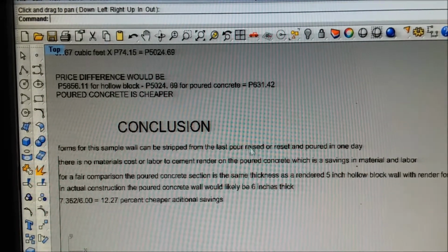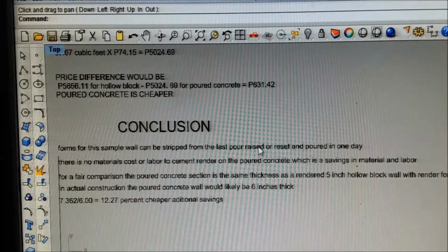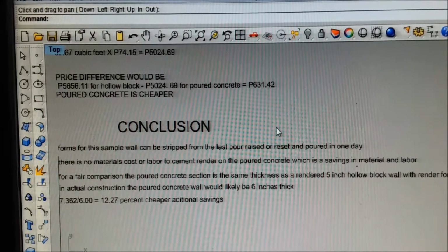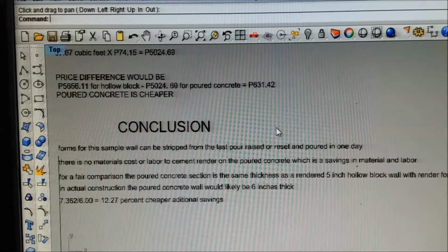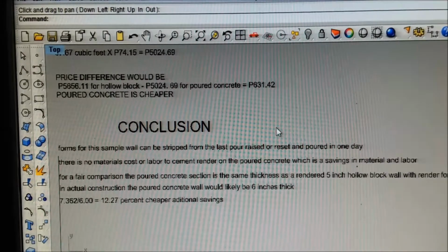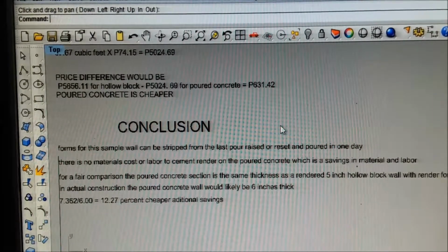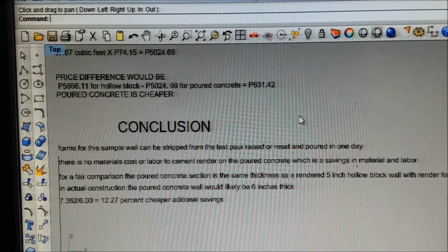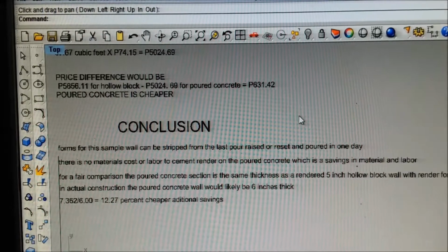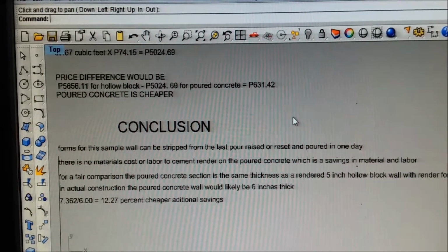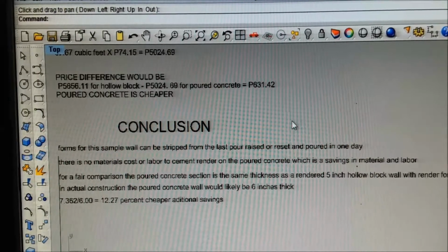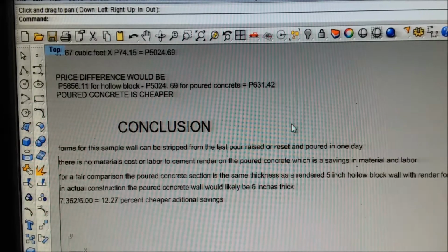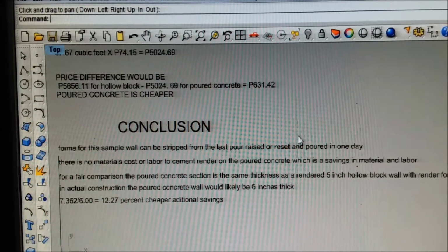We're going to talk about another thing here, because we have another video on slip forming. We did our house with a whole wall section at one time, which is the base tie beam and a wall with a window and the top tie beam and the wall. The walls are 7 inches thick. That's a lot of hydrostatic head. And we basically had 4x8 sheets of plywood. At the end of them, we had a strip like 8 or 9 inches wide, and a 4x4